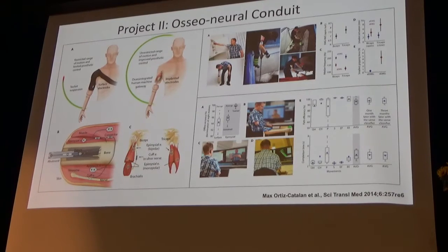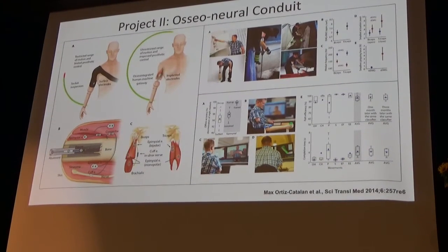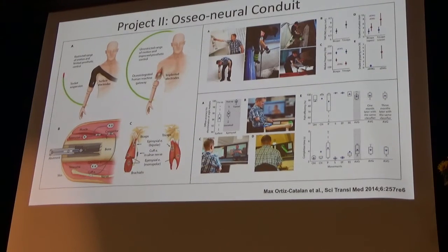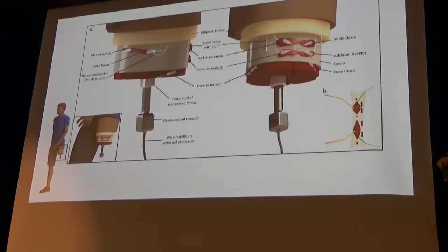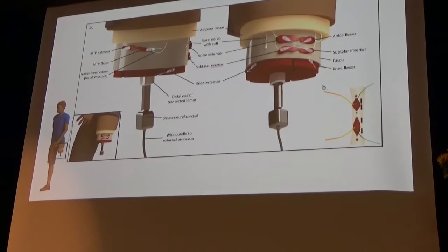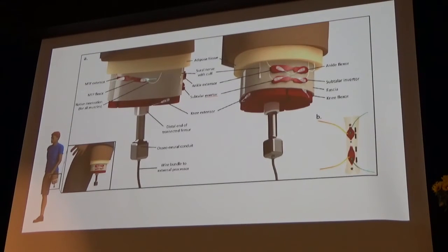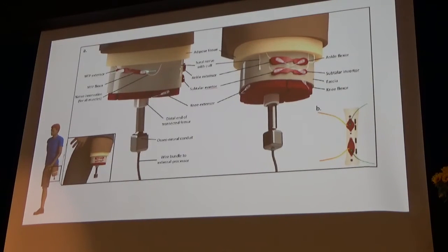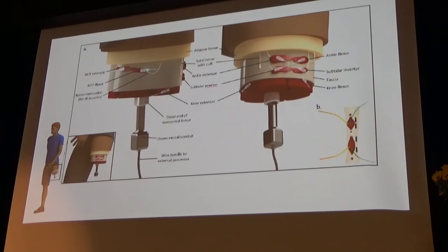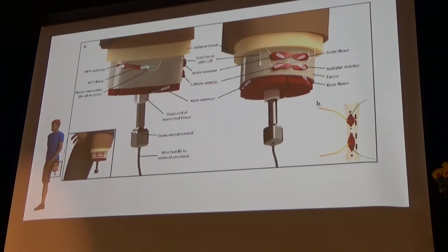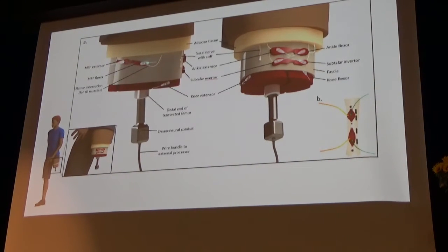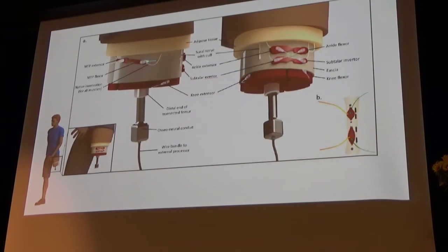We're also working with Dr. Brånemark of Sweden in the realm of osseointegration, not only as a mechanical attachment, but also as a neural conduit. And next year we're going to be doing two planned transfemoral amputations, where again we surgically build up these agonist-antagonist muscle bodies and stitch them to the fascia. Each pair is to be used to control one degree of freedom. So in this transfemoral system, we'll have a powered knee, ankle, subtalar joint, and metatarsophalangeal joint. Four degrees of freedom with cutaneous and proprioceptive feedback.